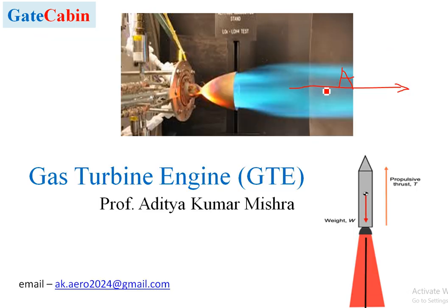Here we are doing an action, and because of this high speed exhaust, jet, gas or air coming out into the atmosphere, this entire system will be pushed in the left hand side direction. So if we want to move in the left direction, we have to generate some mechanism which produces action towards the right hand direction, similar to rocket propulsion.